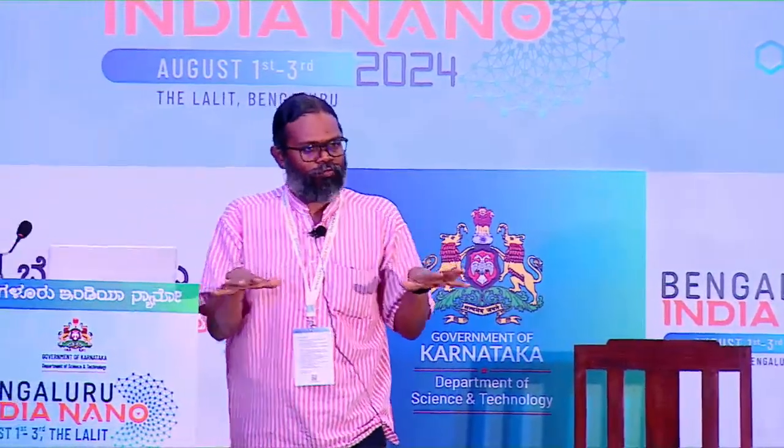But how do you control it? The controlling happens in the process itself, the chemical vapor deposition process I was talking about. You have to tweak your process so that the process is uniform and also repeatable. Okay, so that is process development and process monitoring. That is how we control this.